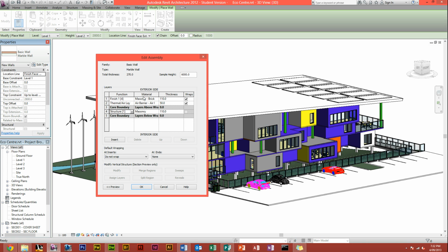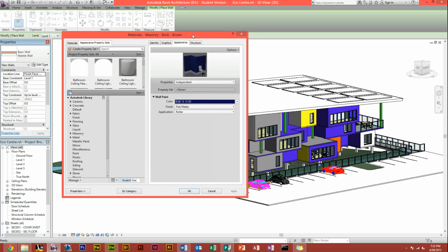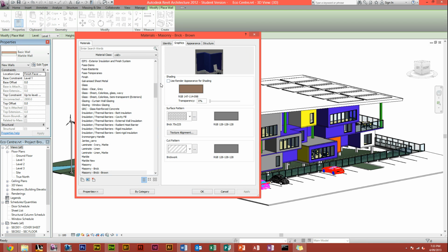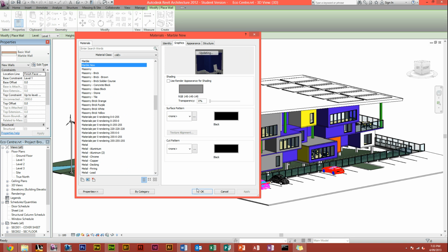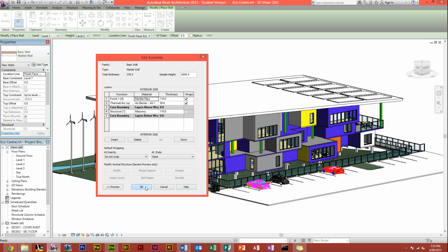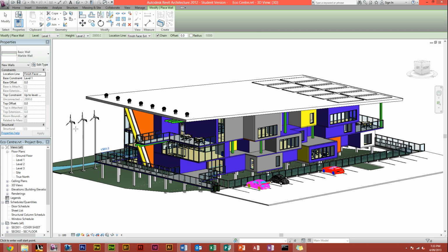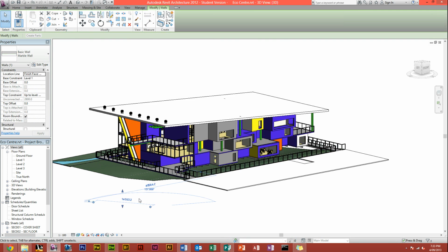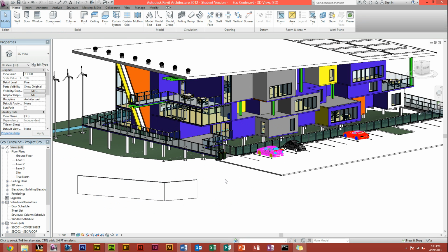Say we want to change the outside to just marble. Click where it says masonry brick, or whatever material was in there, next to Finish under Material, and three dots should appear. Again, you should come up with this page that we saw earlier. So if you head back into Graphics and find the marble one we made earlier, marble new, click OK, and OK again. We've now got the marble wall that we made earlier, so we can put that out wherever we want. And that is our marble wall there. We've pretty much defined it.